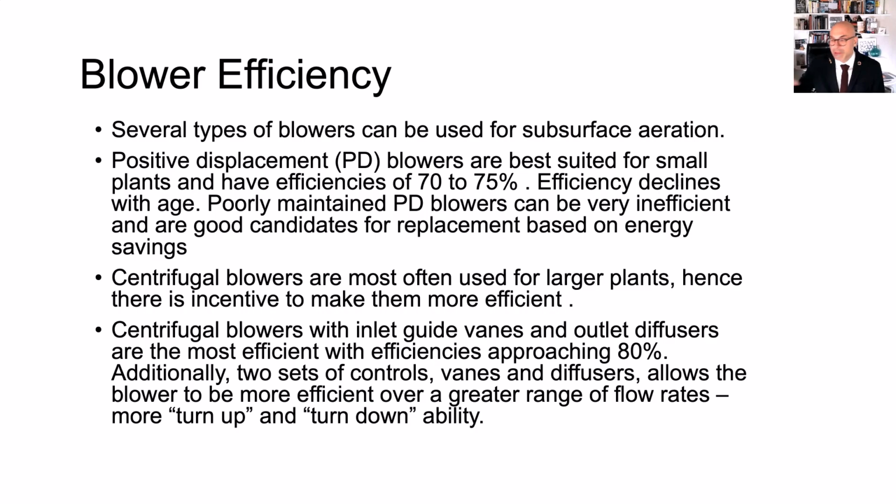But if you take a pipe, you attach it to the discharge and impose a pressure drop by, say, putting that pipe into the water, okay, now there is the hydrostatic pressure. Now the velocity is converted into pressure, Bernoulli. So what happens is you give up some of the velocity and you release that energy in the form of pressure. So some blowers have the ability to discharge a wide latitude of airflows, okay, but at the expense of pressure. And that will be the case of centrifugal blowers.